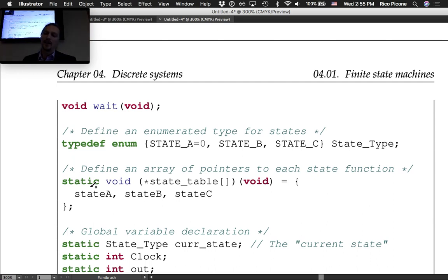The way that we've set this up, it's not that ARM does not do that, but the way that we're using ARM with C, we have control over that. So in our wait function, we can predict for this processor how long it should take. If you ran that same function on another processor, it might not be deterministic. But if you have an ARM system and use just the commands that we're going to use in C, and implement it this way, it's deterministic. You can get into trouble if you try to do timing on just any old system, like a PC.